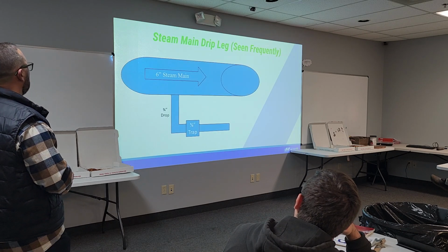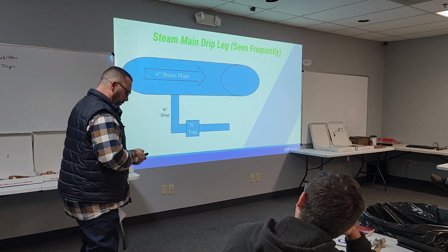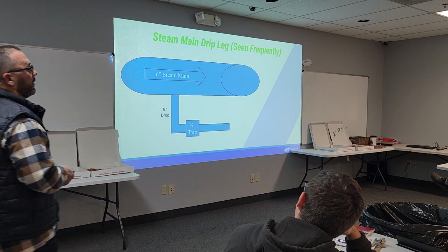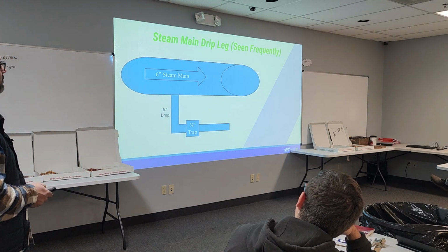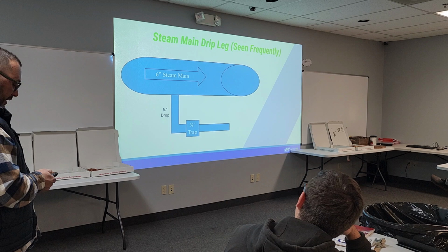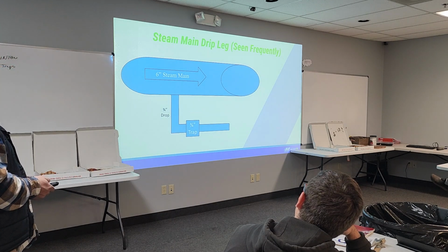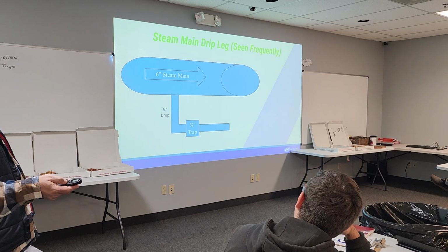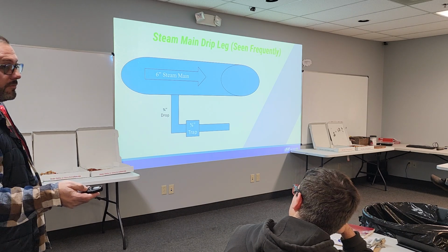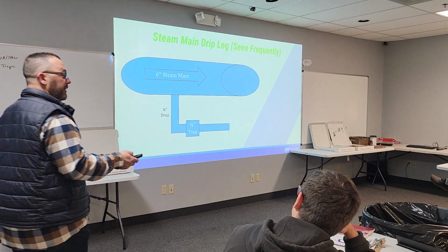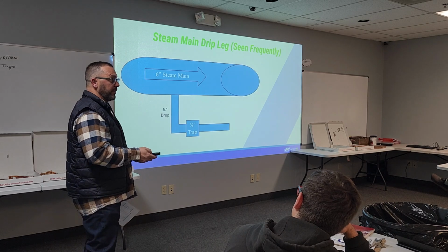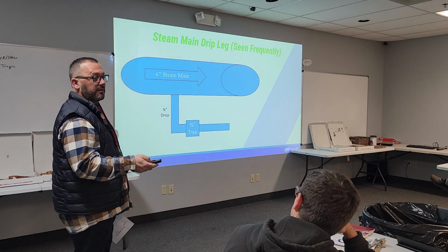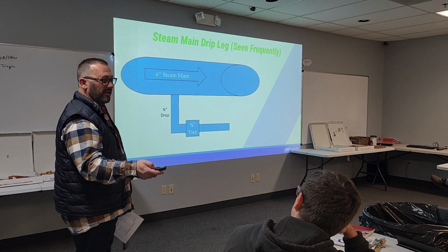So this is an important one. So drip legs, dirt legs. A lot of times, I just told you that, hey, a drip trap, it's a 1/2 inch or 3/4. They do make a 1-inch TD trap. There's probably not an application in North America for it, despite the fact that we sell them a lot. And we tell people, hey, that's really oversized.